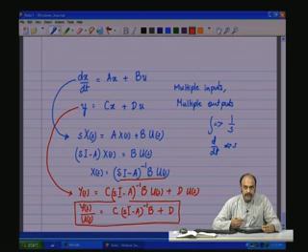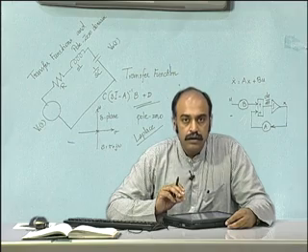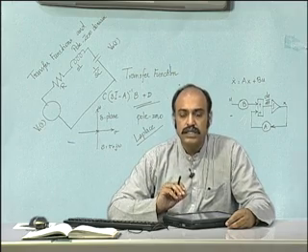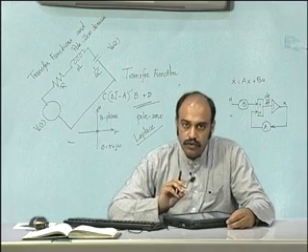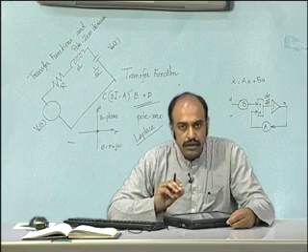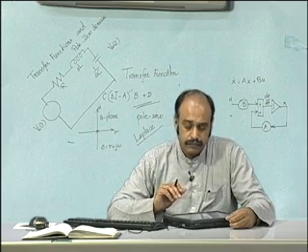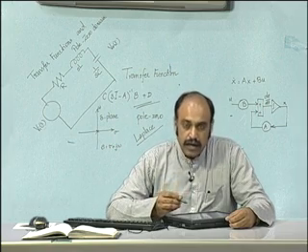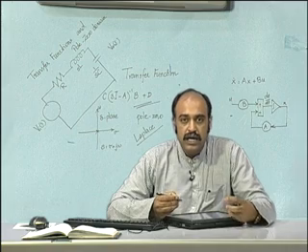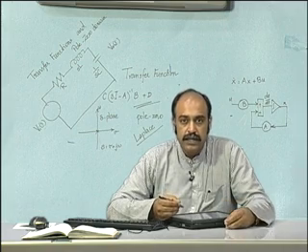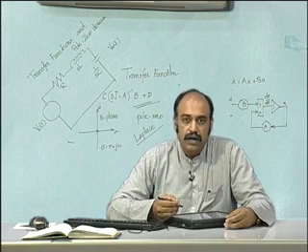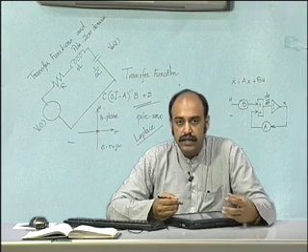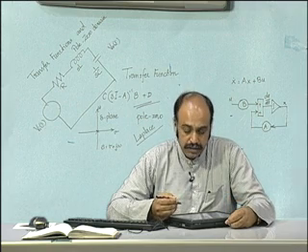And once the transfer function is known, the roots of the denominator polynomial are the pole locations in the S plane, the roots of the numerator polynomial are the 0 locations in the S plane, and they give an idea about the damping properties, the decay properties of the system for any excitations and disturbances.